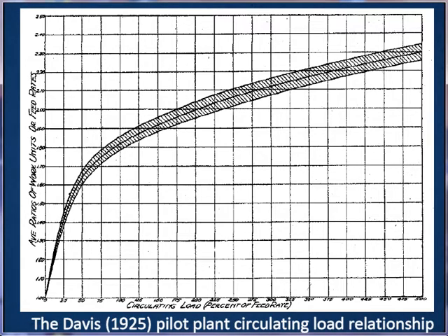A very interesting observation about ball milling circuits is that operating them at high circulating load ratios makes them much more efficient. We can produce 2 to 3 times the amount of new product size material by operating in closed circuit with a circulating load of 300 to 500% than we can in open circuit. The question is, why?